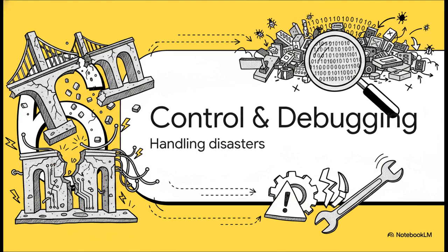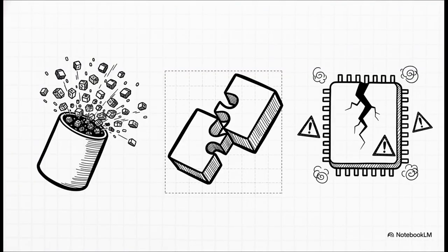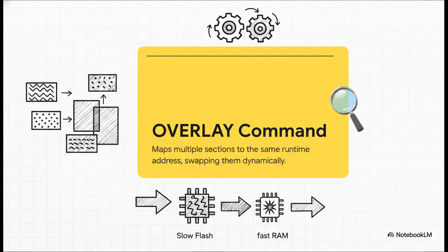Finally, let's jump to section 6, advanced control and debugging. Let's talk about handling some common disasters. Because look, when you're dealing directly with bare metal hardware, errors aren't just bugs, they're catastrophic. Miscalculate a length in your memory block? Boom, section overflow. Forget to align a memory address to a 4-byte boundary? You will trigger a hardware alignment fault that instantly bricks the entire startup sequence. Trust me, absolutely nothing ruins a Friday afternoon faster than a silent, unforgiving hardware crash caused by one single misplaced linker constraint.